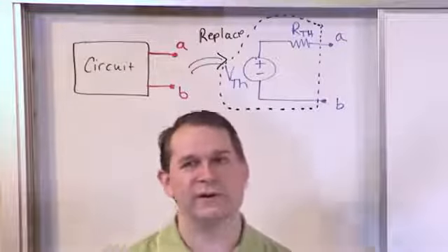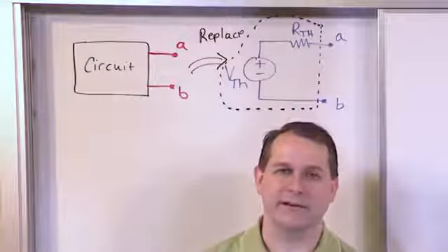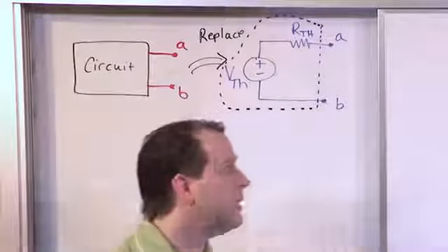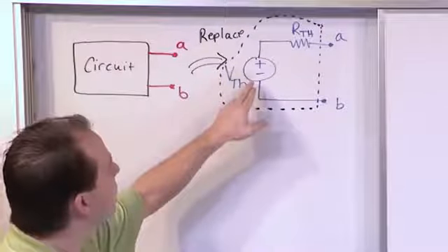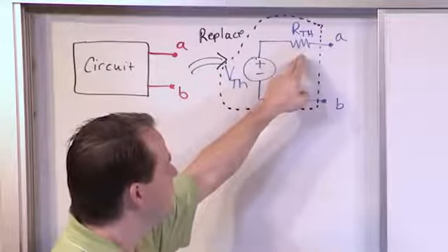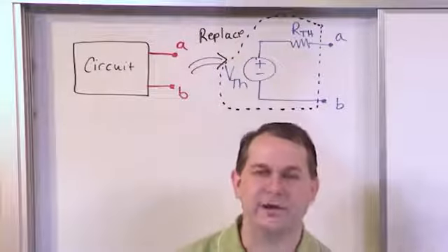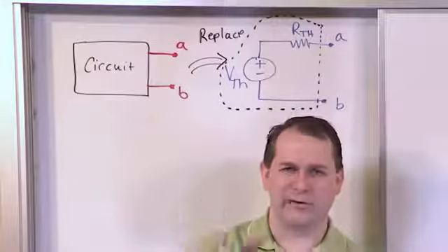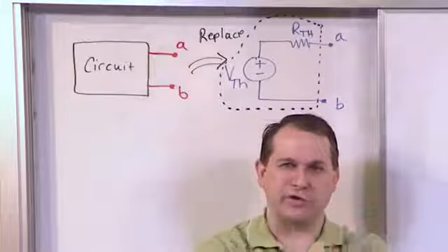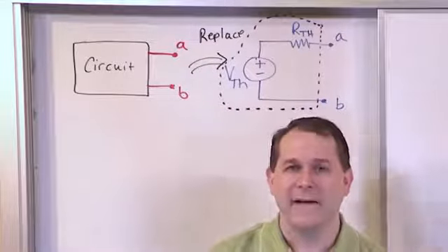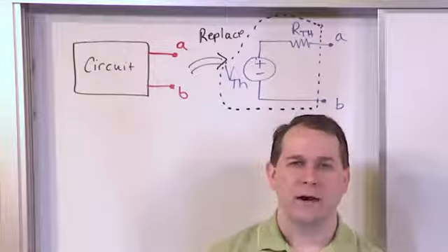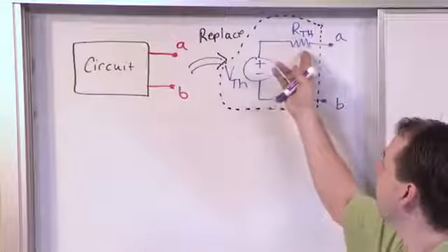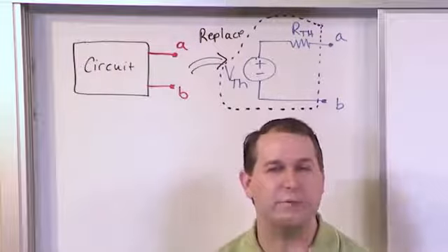And what the Thevenin theorem really says is that any network of resistors and sources of any type can always be rewritten in terms of a single voltage source and a single resistance. And when you think about it, that is crazy that you can do that. I can have 39 current sources, they don't have to be well-behaved circuits, all connected in crisscross, spaghetti network inside, and lots of resistors going everywhere, right? It may be hard to analyze, but any resistive network like that can always be rewritten in terms of a single resistor and a single source. That's pretty darn amazing, right?